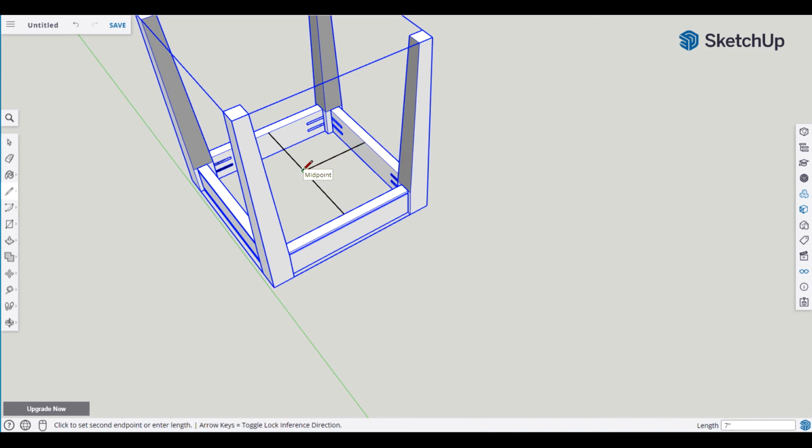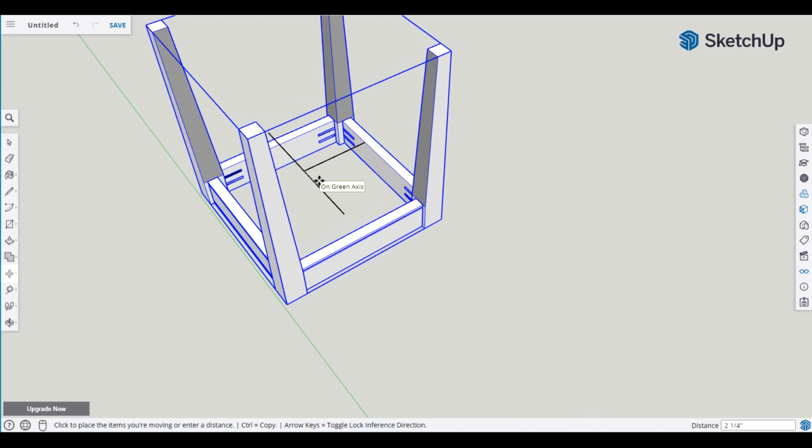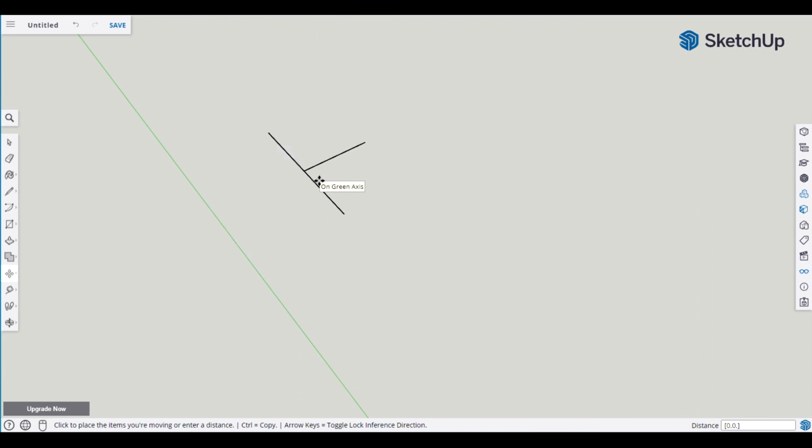And I'm going to stop right there, hit the space bar. Now I'm going to select M and go to that center point, move it. I'm going to type their numbers, but one's going to be different to get it to rest on top. So we do open bracket, 0, 0, close the bracket, and that's going to put it on top of the table. Hit enter, space bar, and then select this, delete,